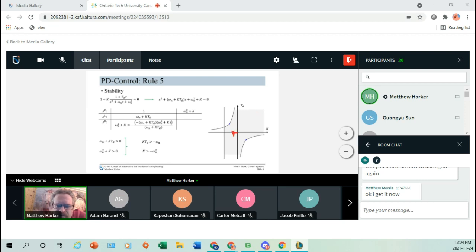So this says we have this really strange stability zone where we could actually have negative parameters. And this is just to say that these are the values that are going to keep the locus on that negative real half of the complex plane, right? It doesn't mean you want to set your parameters to any of these things here.